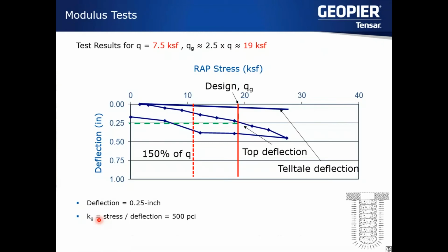And I will come back to that in just a moment. But thinking about that, that gives us two stress strain curves here. What we're looking at is a modulus test result from the data that we come up with. We have our stress strain curve here, which is the displacement that we measure at the top of the pier, those two gauges that are on the steel plate.